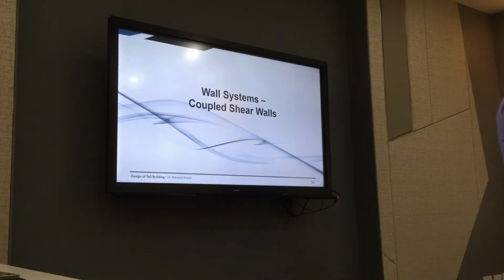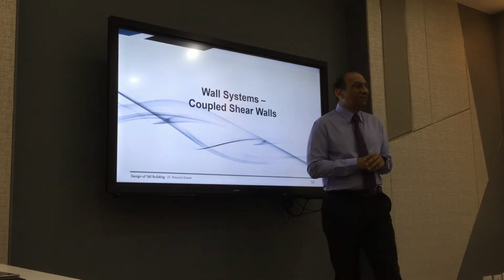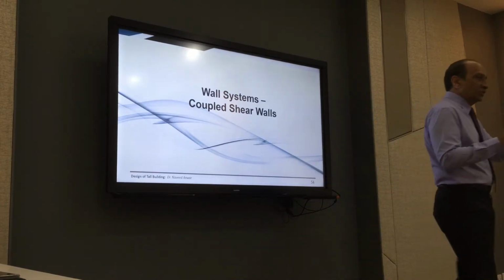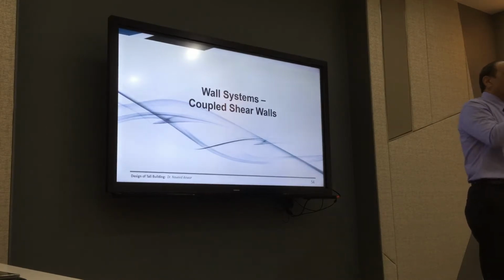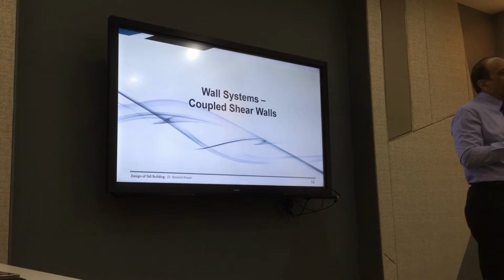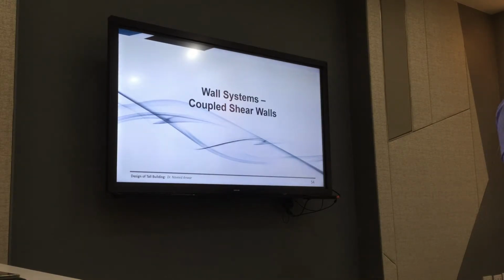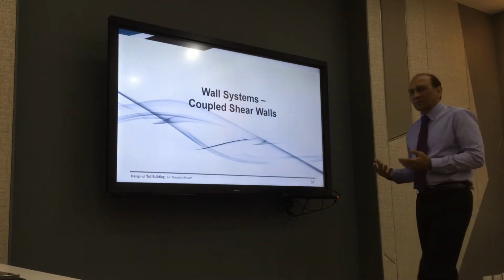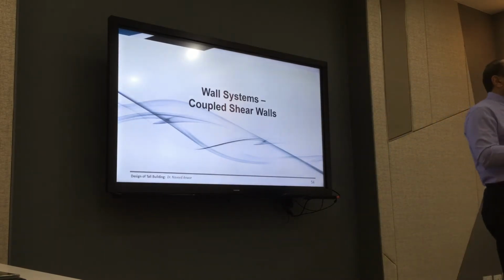So, combining the shear walls and frames is a very efficient way to solve this lateral loads response problem. Because we get two benefits. One, as I mentioned to you, the deformation pattern is different, so they push and pull at each other, reducing the deflection. Second is that you convert the bending moment into axial forces through the spandrel effect or the outrigger effect. And that is also beneficial because you reduce the bending moments and you also reduce the displacements, right? So that is a good thing.